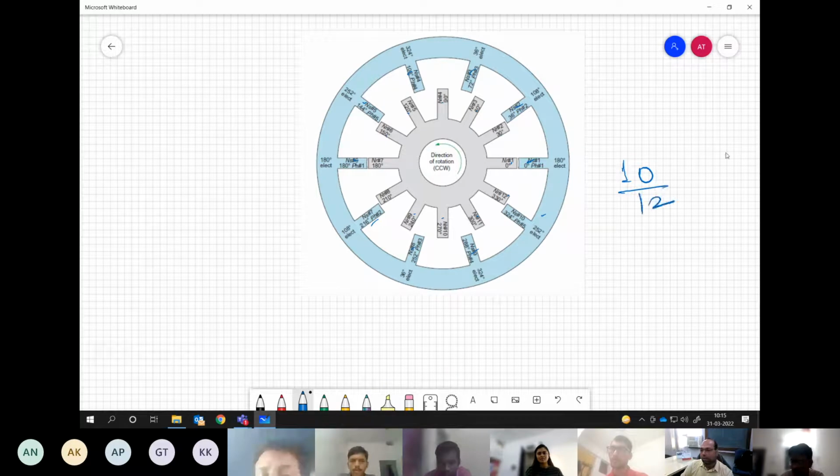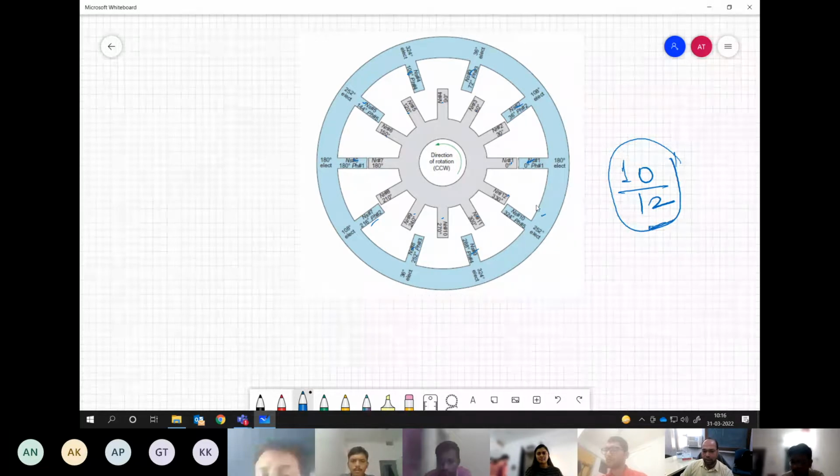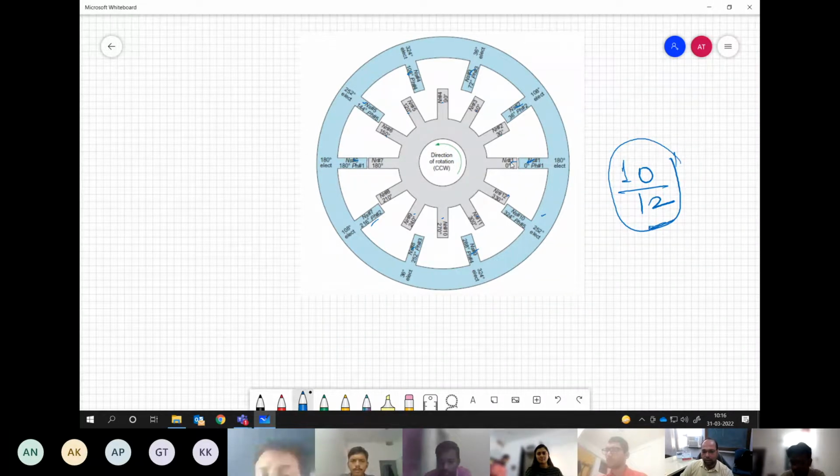12 rotor poles. So now this is a kind of SRM, a more practical SRM where you have a 10 by 12 configuration, and let us see how many phases we are able to get. With respect to this particular position of the rotor, these are the stator poles which are completely aligned with the rotor pole, correct? In another position, this is partially aligned here and here.